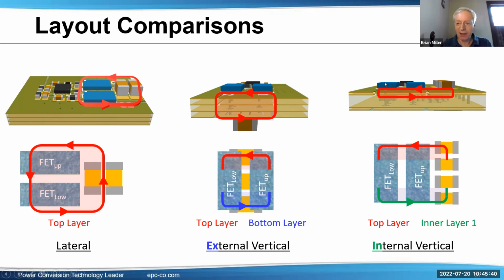But yes, again, it's basically putting all the parts on the top in a row using the first inner layer. The second part of the question is related to the gate drive. Is that right? Let me go back and find it. I'm sorry. Yes, no, it's fine. If we keep a bootstrap supply, it will charge capacitors, which will slow down the higher switch gate drive, right?